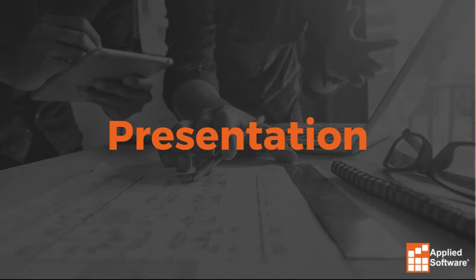My go-to strategy for building office deployments is to get into custom UIs. There is a Dynamo package called Data Shapes, and it includes a bunch of UI nodes. These UI nodes allow us to essentially have dialog boxes pop up in Revit to control the Dynamo graph. You never open Dynamo.